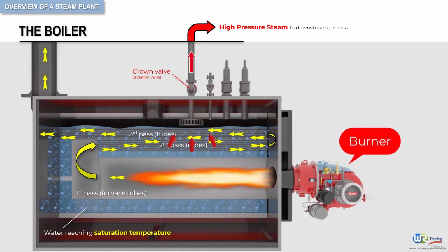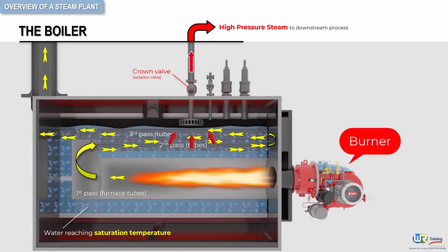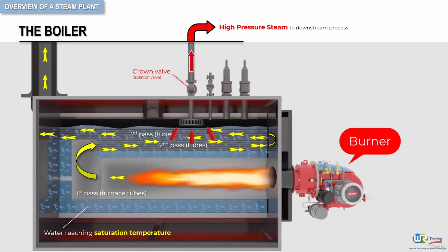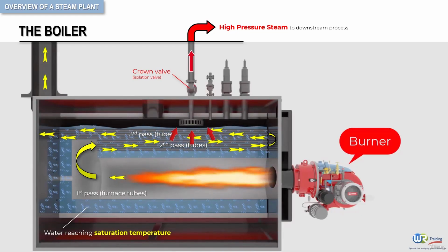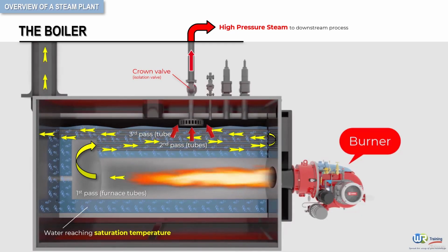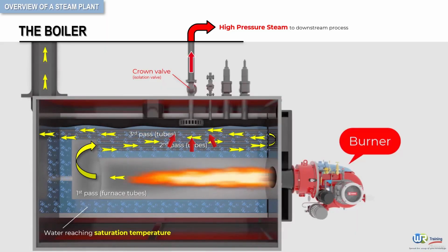Now, as long as the amount of steam being produced in the boiler is as great as that leaving the boiler, it will remain pressurized. The burner will operate to maintain the correct pressure. This also maintains the correct steam temperature, because the pressure and temperature of saturated steam are directly related, and this will be explained in detail further ahead.